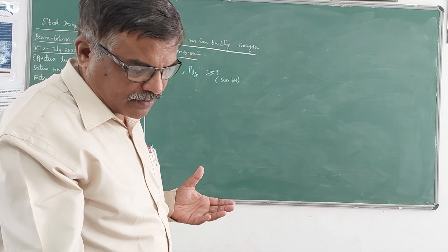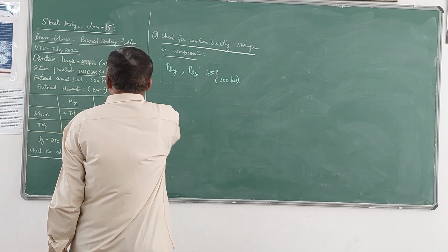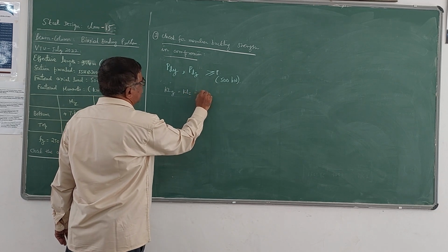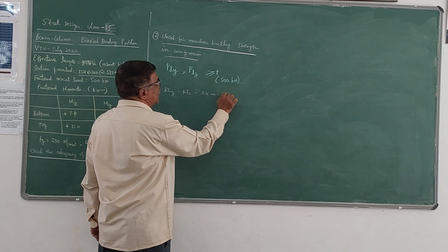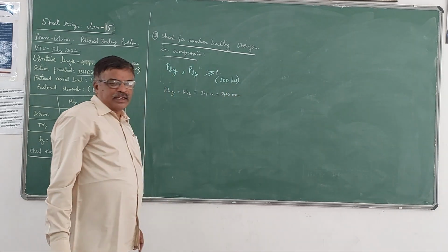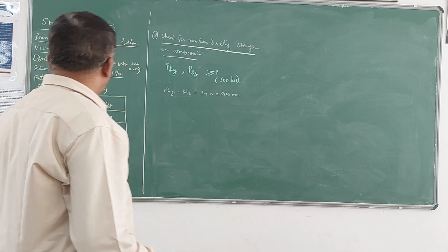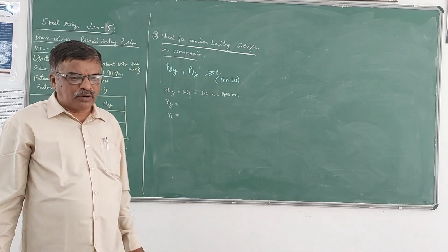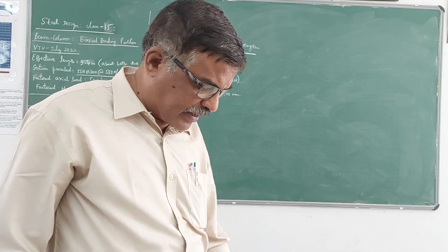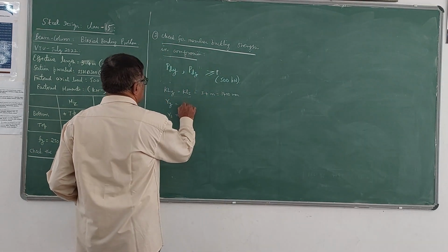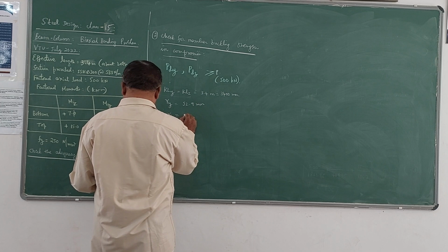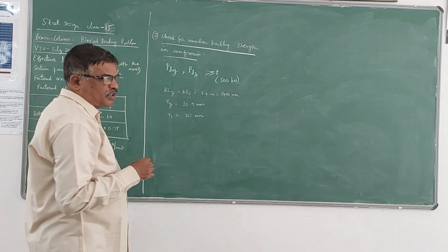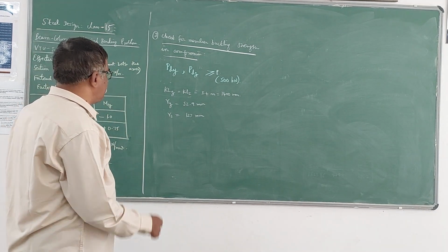In another way, whatever beam column is given is treated as a column and checked for compression. Here he has given the effective length, KLY and KLZ, both 3.4 meter or 3400 mm. Now we need the values of RY and RZ, the radius of gyration of the ISHB 300 about the Y and Z axis. From the steel tables, RY is 52.9 mm and RZ is 127 mm.